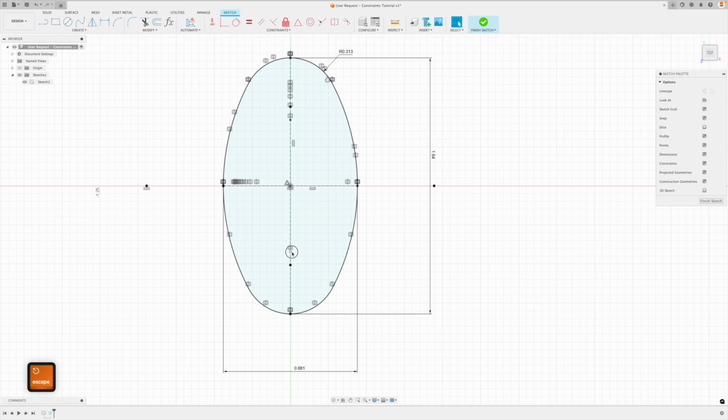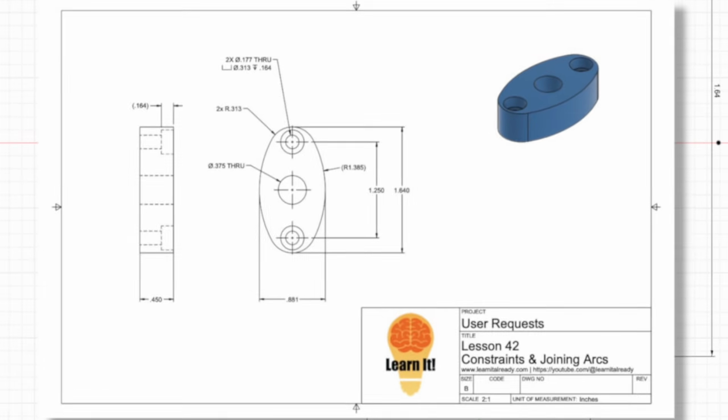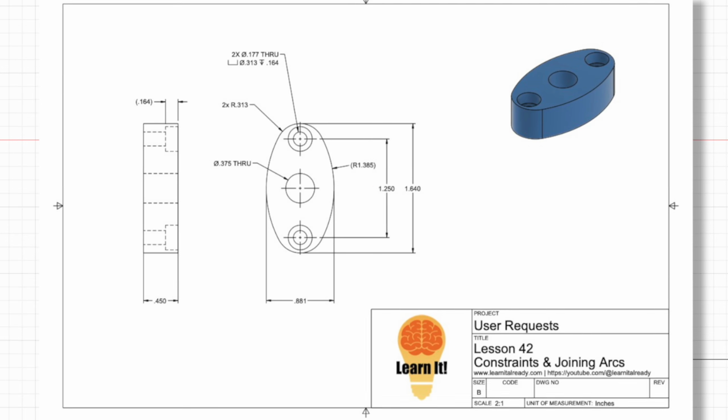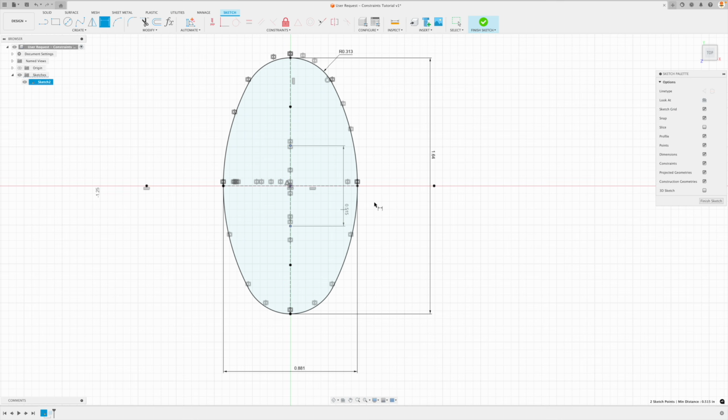And now you can see as I move one in, you can see they are symmetrical to each other. So I'm just going to move this out. Doesn't really matter, actually. We can leave it on the inside. But look at the distance between those holes. Do you see? 1.25. So I'm going to pick those 2 points, move it on over, 1.25. And now, is everything constrained? Yes, it is. Sketch 2 is fully constrained.